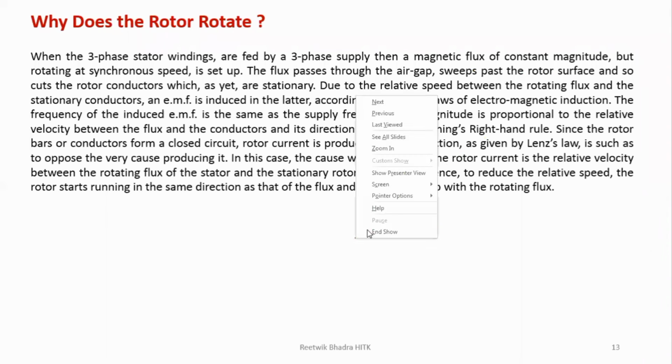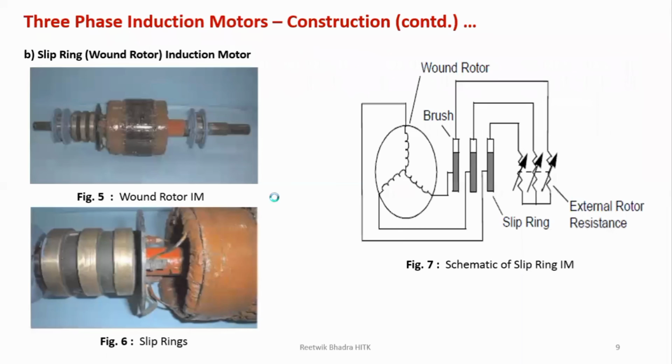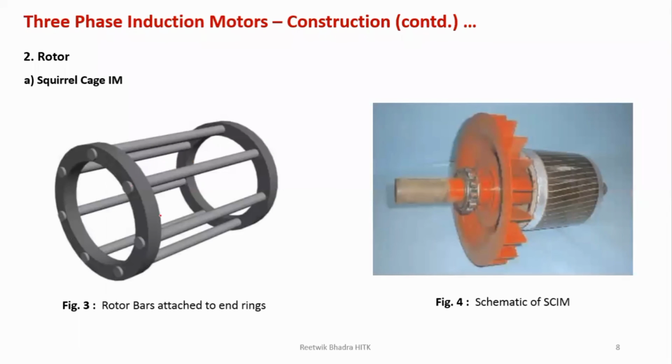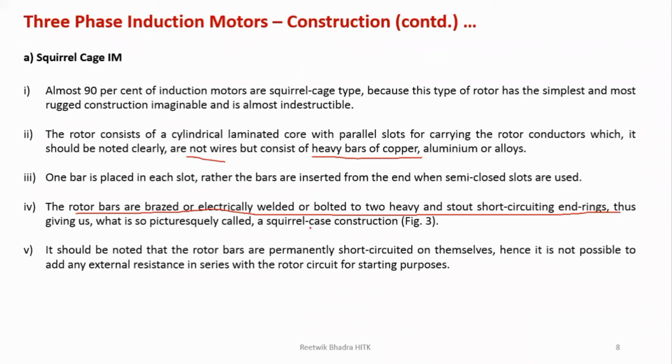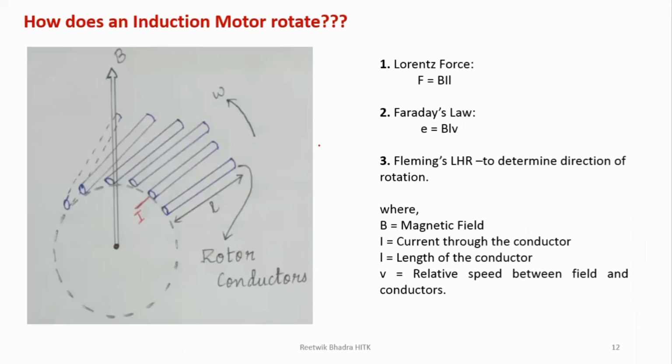So you can just look, this is your rotor. Okay, this is rotating in nature. Now this is a stator. Within this there will be the complete rotor structure placed. Now there should be an air gap between the two. When you are giving three-phase supply, some flux will be produced. That flux lines will pass through this rotor conductors also. So it will cut the rotor conductors. And there should always be a gap between the two. Otherwise, how will this internal structure rotate? So there should be a gap also. So that is your air gap, which is called over here.